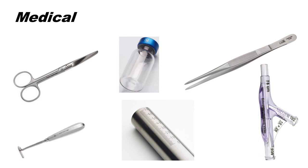Medical is also extremely popular due to the fact that the fiber lasers produce that annealed mark. So bacteria can't grow when the material or metal is not actually subsurfaced. Inking processes typically are not legal in this situation for the fact that any one of those type of components can come off over time. An annealed process is a perfect solution for the medical industry.